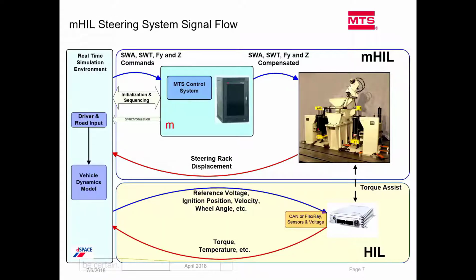Another real-time hybrid simulation in ground vehicle we developed is this steering system hybrid simulation system. Again, the physical substructure is here, the steering column and the rack, and it's connected to an MTS 5-channel test system. Again, you have a dSPACE, and there's a CarSim model running, and then there's a roll tire, all those things.